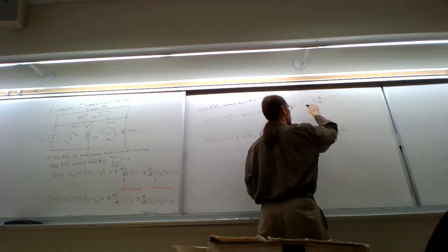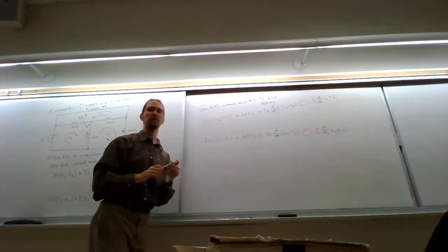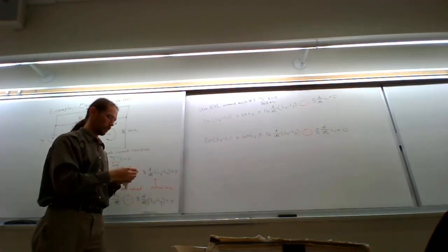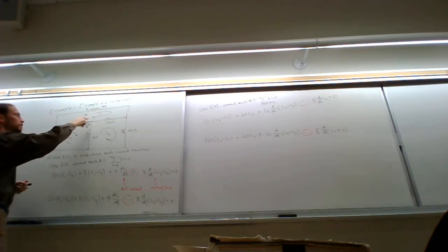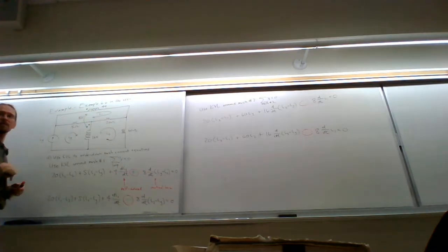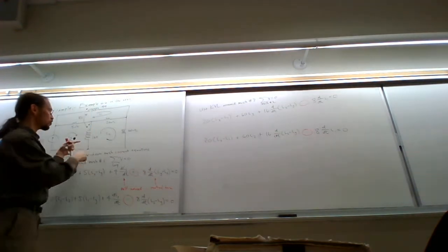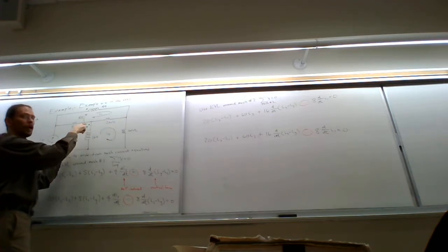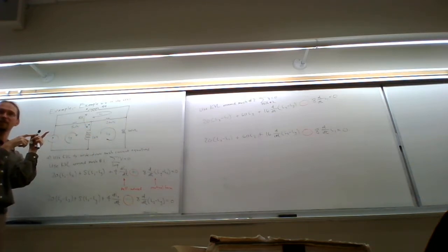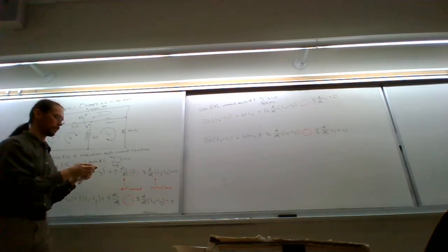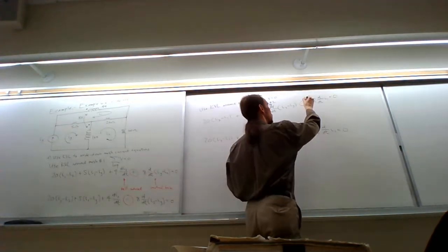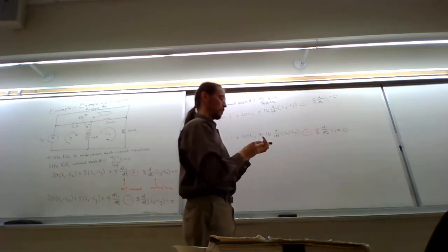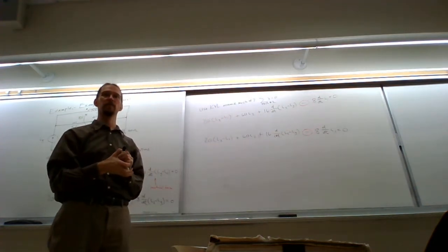The question is, what's the sign on these? Now over here, I1, it is entering its dotted terminal. I2 minus Ig, I2 is the dominant current. It goes through the inductor, and then it goes out through its dotted coil, or its dot. So this one's entering, this one's exiting, which means that has to be negative.